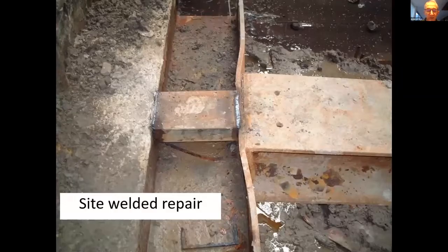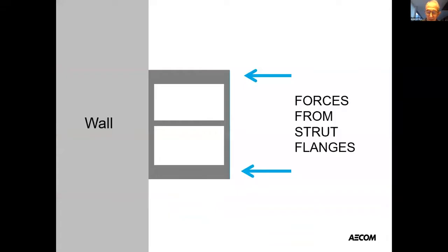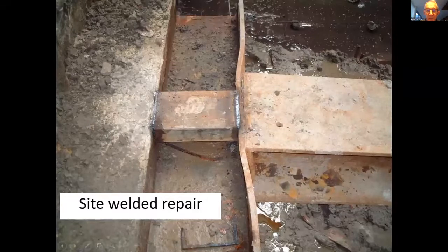But later on, just before the failure, at the location of the failure, the same deformation happened. And you can see it was more than that: this strut coming in from the right has deformed this flange, and the end plate is deformed. And someone has welded in a short piece of channel section in order to do a site repair, instead of making a proper connection, which would have had a gusset plate in here and a gusset plate in here. If you're familiar with structural steel, you know what I'm talking about.